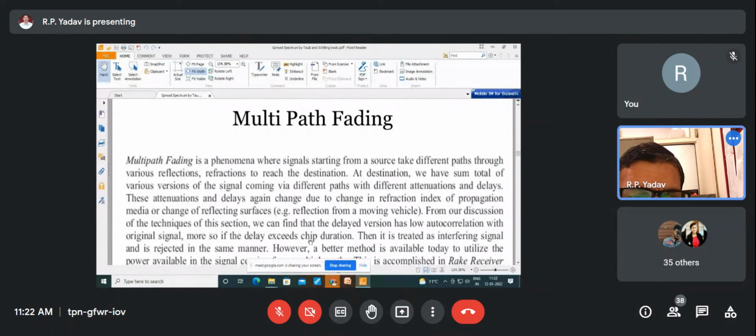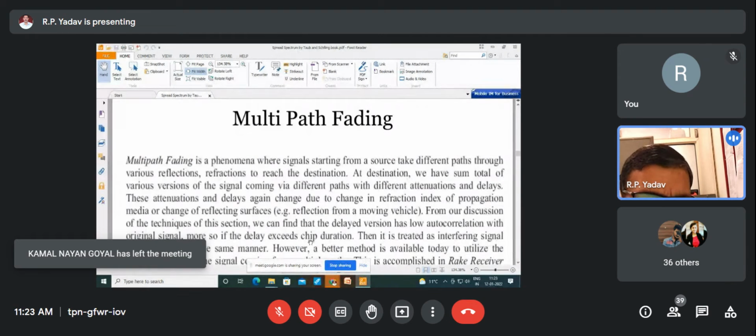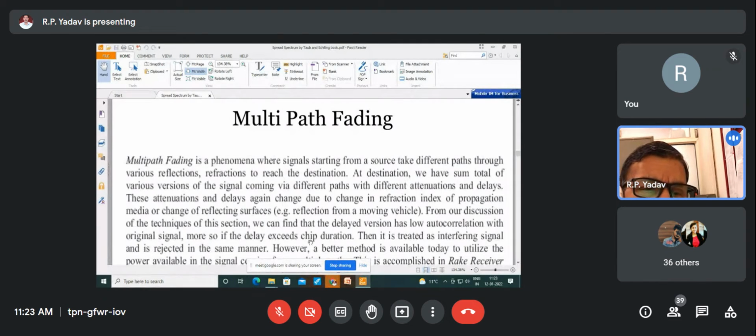So what are the reasons for that fading? In a very elementary form, you can understand it this way: the signal in free space comes through different paths. There may be a line of sight path, and there will be reflection paths from buildings, cars, trees or anything. The signal reaches the user through many paths, and when these signal amplitudes combine together at the subscriber's mobile, they may produce very high constructive interference, or destructive interference. That means the signal amplitude reflects an addition of these signals. That is multipath fading.